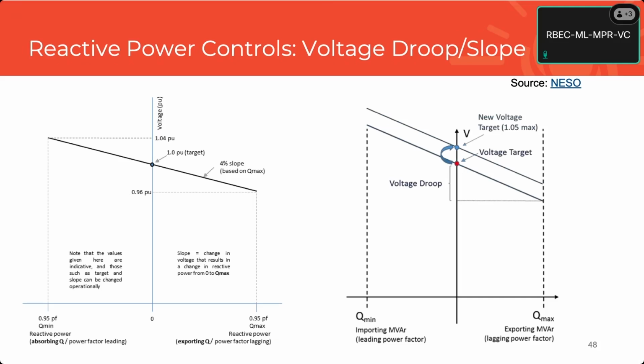So as soon as the voltage goes above 1 per unit, we're going to go all the way to the left. If we go 1.001, we're going to go full reactive power, inductive, and try and pull the voltage down. And we would go all the way to the right the moment that the voltage came down to 0.999.